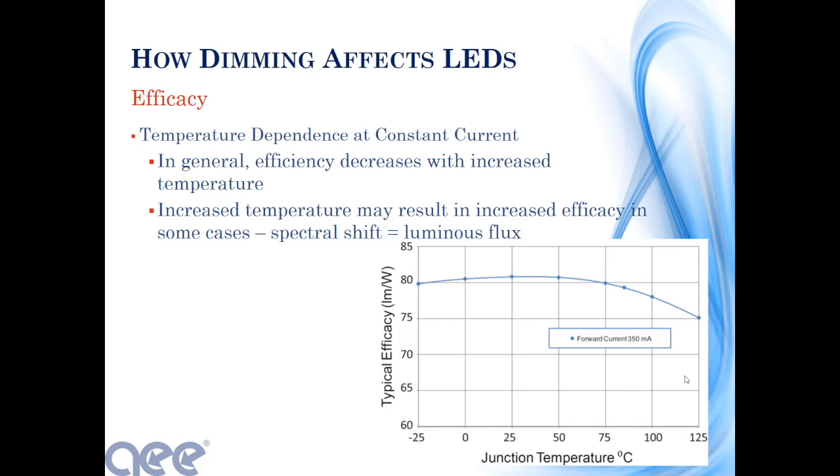In this case, if the temperature varies and the current is constant, the efficiency will decrease if you have higher temperature. Remember, LEDs like the cold. They put them in all the freezers and stuff. You go into Sam's now, you walk down the aisles, and they're all pixelated, but it's light. And then the nice thing is they're controllable, so you can put them on an occupancy sensor. Well, LEDs like the cold. They don't like the heat so much. Heat sinking has been a huge issue with LEDs.